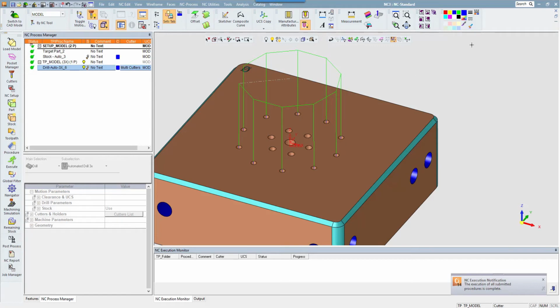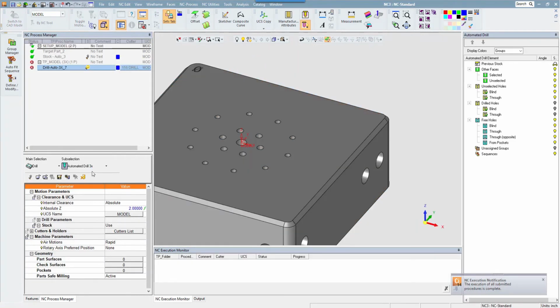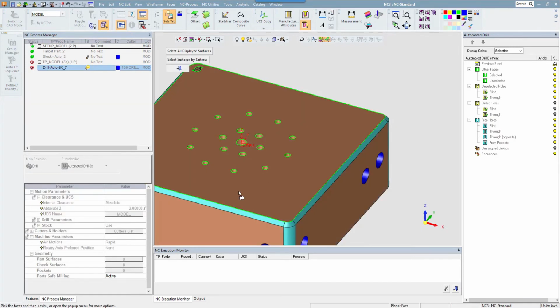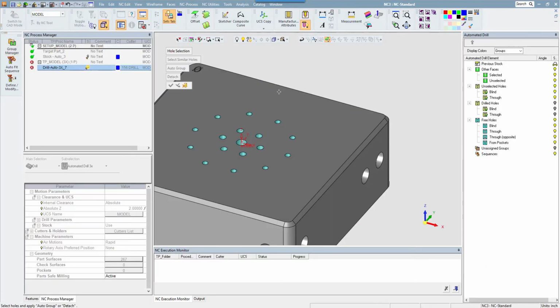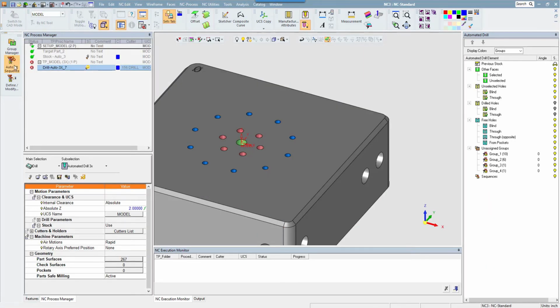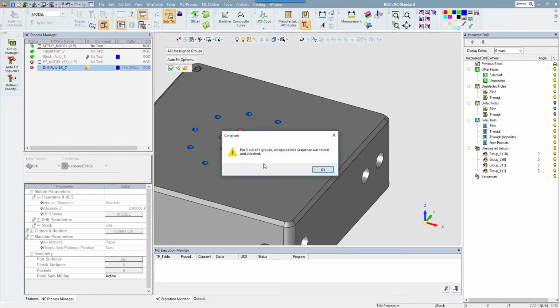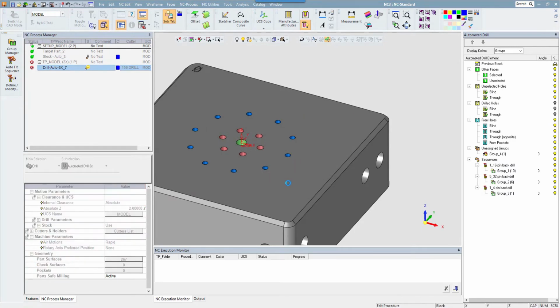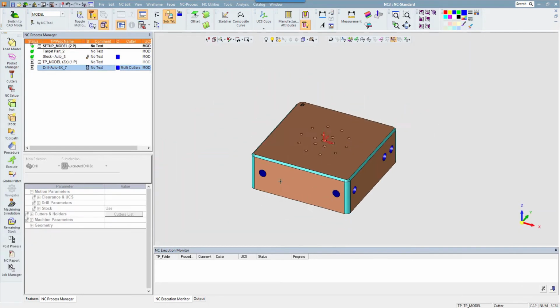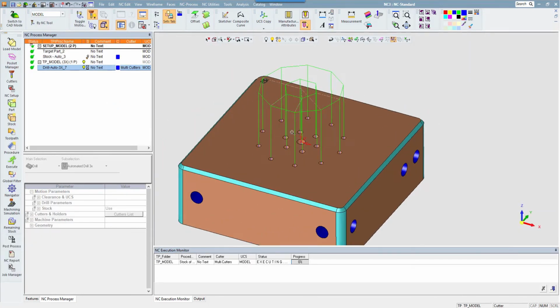Now, since we just made that sequence, we can actually delete this, create it again. And this is a good way to test the sequence that you made if it's any good, because if you miss something, it may not fit. If it doesn't fit on what you just had, then you definitely got a problem. So we'll just pick all these. Route Manager, Control A, Auto Fit, green check, OK, save and calculate. We have a part. That setup is done.